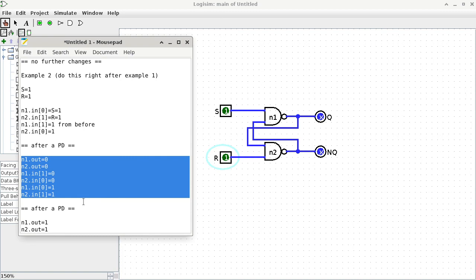So it's going to go 1 and then 0 and then 1 and then 0. The amount of time that it stays in each state has to do with the propagational delay of the logic gates. So if the propagational delay of the logic gates, meaning how much time it takes for the input to become effective, is like 5 nanoseconds, then we're going to see 5 nanoseconds of 1, 5 nanoseconds of 0, 5 nanoseconds of 1, 5 nanoseconds of 0. There is no steady state in this case. Is that okay?